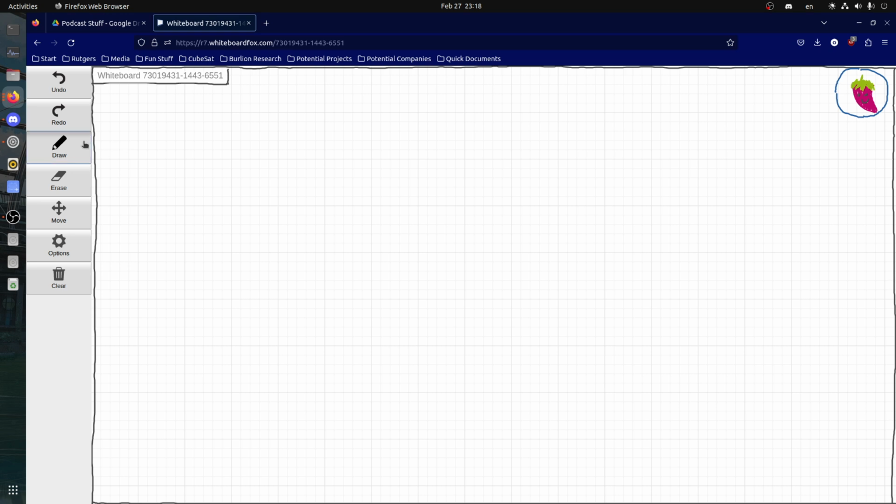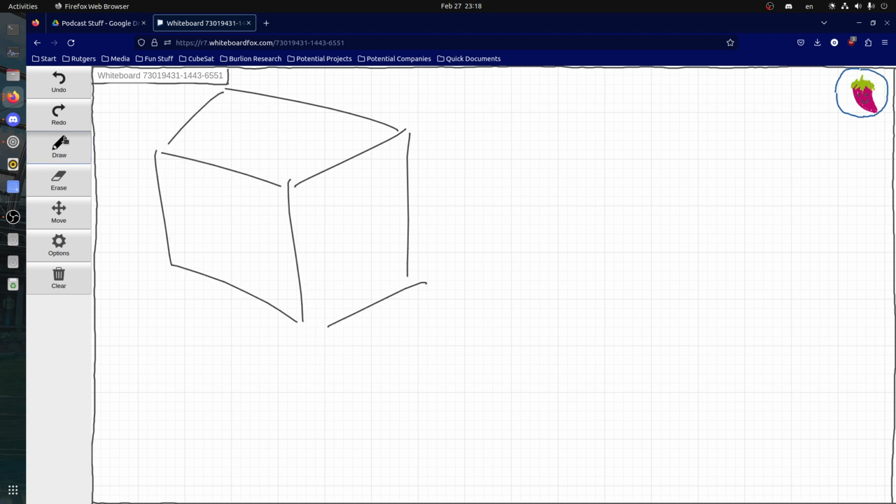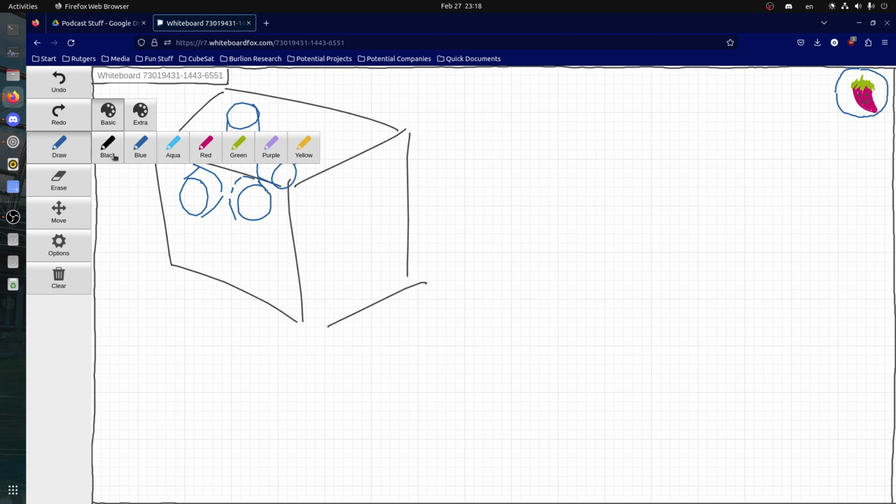So to accomplish this, the ADCS has several components. The first main component are the reaction wheels. The reaction wheels are usually three wheels oriented along three perpendicular axes, and usually they have one extra one for redundancy, but three is the norm for small satellites. Four is for missions that have a heavy emphasis on the ADCS, and it's not allowed to be a failure point, such as our mission.